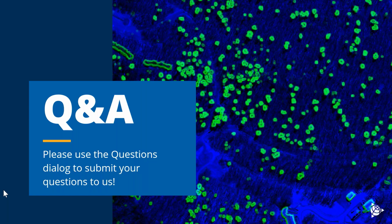Okay, and we have one more simple question. What is the slope DTM? What is the difference with a typical DEM? So the DTM I used was a digital terrain model, but instead of using the ground returns to make just a bare earth surface, what I used was the last return layer, or the last return points from the Lidar.